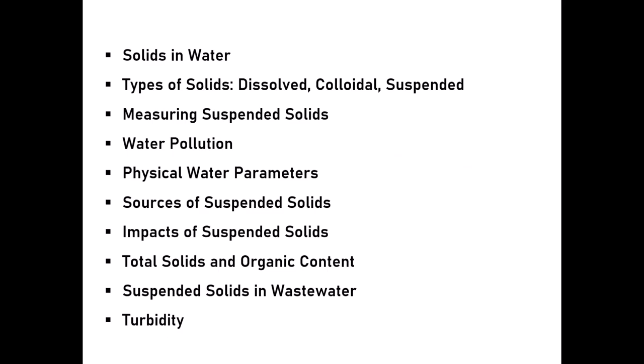It is measured with a turbidity meter calibrated with formazine, with results in FTU or NTU. NTU, nephelometric turbidity unit, measures light scattering. Always check size, type, and concentration of solids for treatment design. Suspended solids affect health, aesthetics, and treatment efficiency. Turbidity, not color, indicates presence of fine particles. Measuring physical parameters is a first step in water quality assessment.